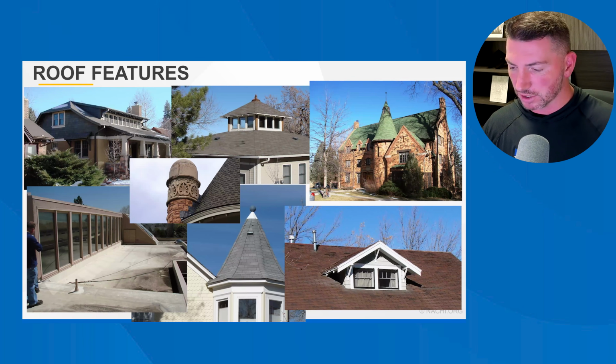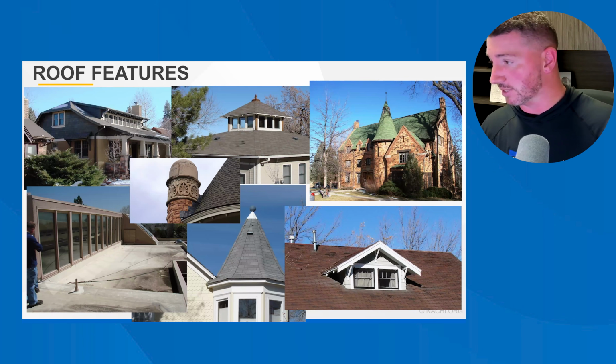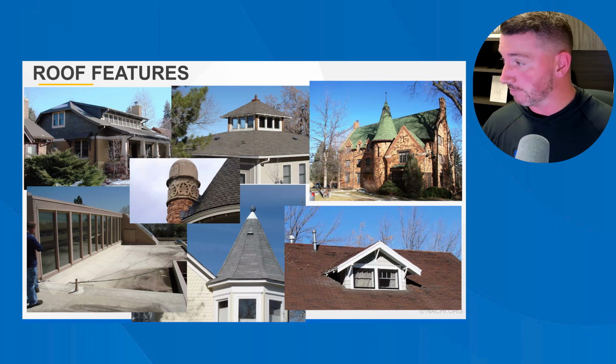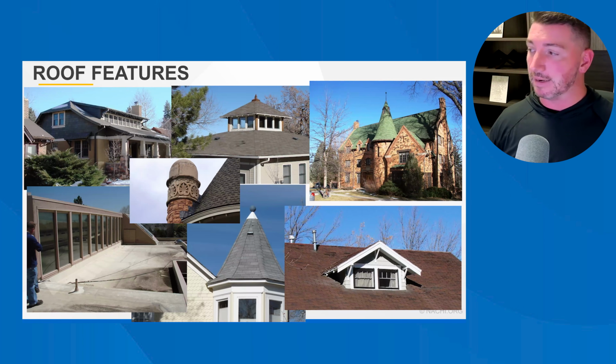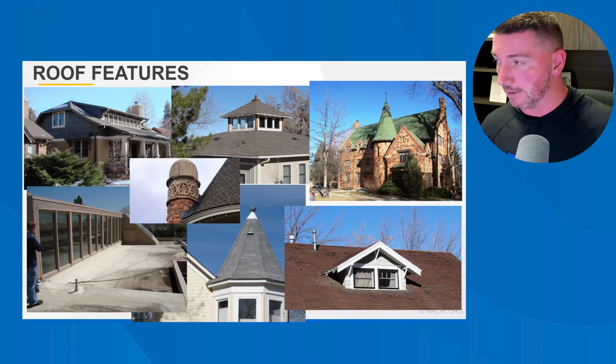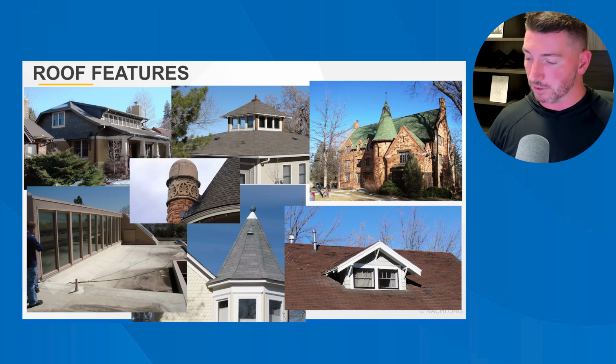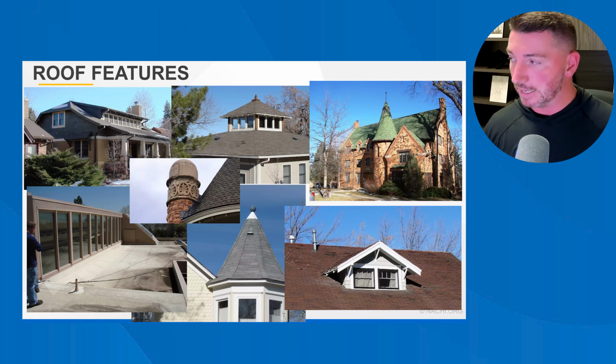So, inspection concerns include flashing at the round sidewalls in areas at which conical roofs intersect with roofs of other shapes. Specially shaped crickets or flashing may be needed to provide long-term protection against leakage. You can see that green looking roof, maybe a church or a library or something. I guess it could be residential. Well, there's a bike in the yard, so maybe it's residential. But behind that, you can't see it in this photo, but they definitely have a special shaped cricket to divert water away from just building up behind such a big conical roof intersecting with that main gable roof.